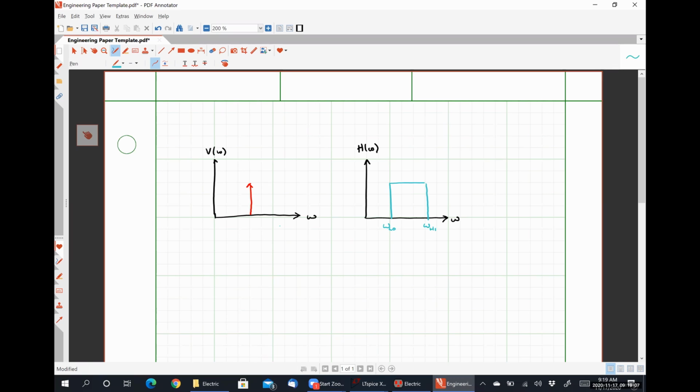The reason why it works on a guitar is because of all the different multiple frequencies that get generated when you pluck a string on a guitar. But if you make an oscillatory circuit that's effectively only oscillating at one frequency, your filter isn't going to be moving the resonant frequency. I guess what I'm getting at is you need to be able to move this resonant frequency, not this one.